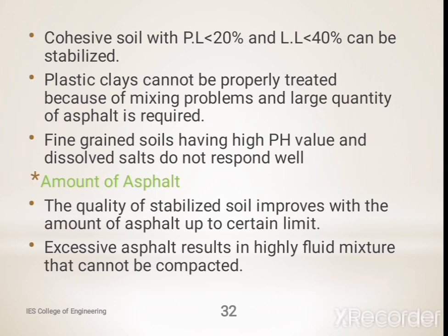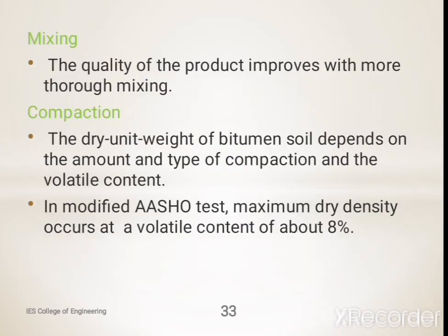The next factor is amount of asphalt. The quality of stabilized soil improves with the amount of asphalt up to a certain limit. Excessive asphalt results in a highly fluid mixture that cannot be compacted. The next is mixing. The quality of the product improves with more thorough mixing. Mixing needs to be done thoroughly.